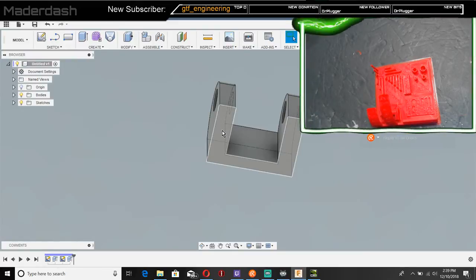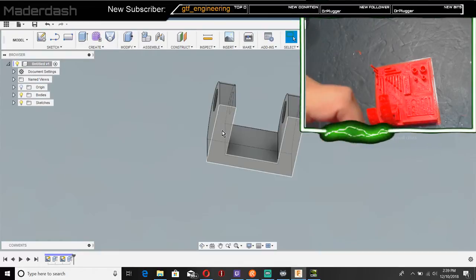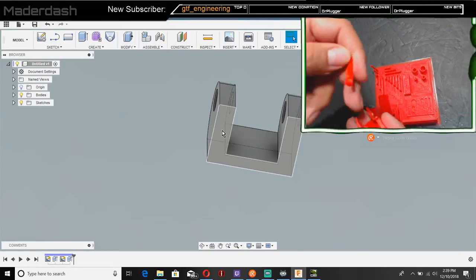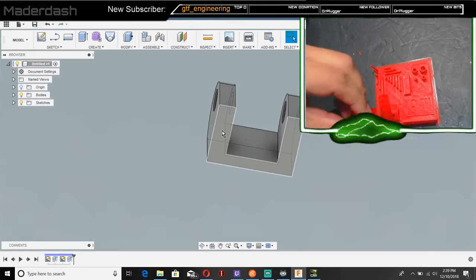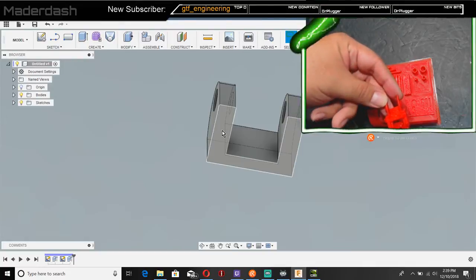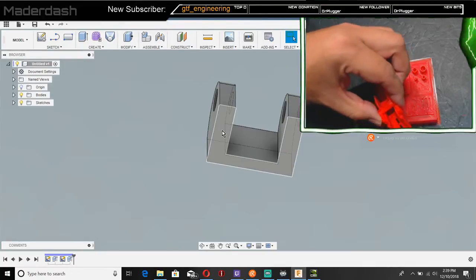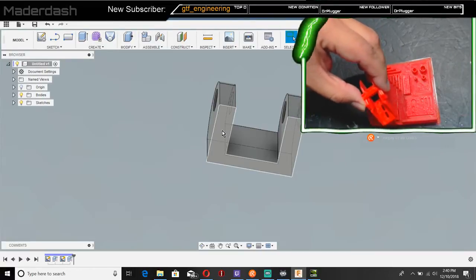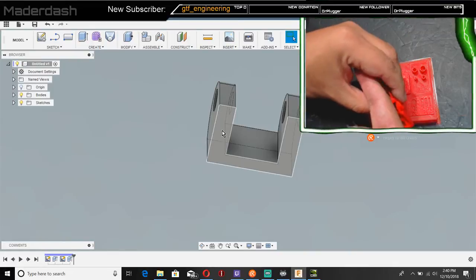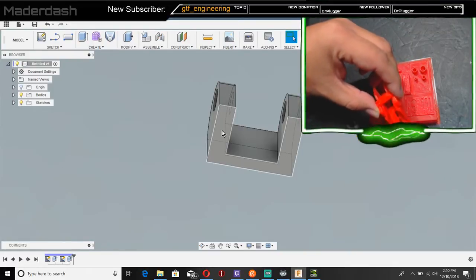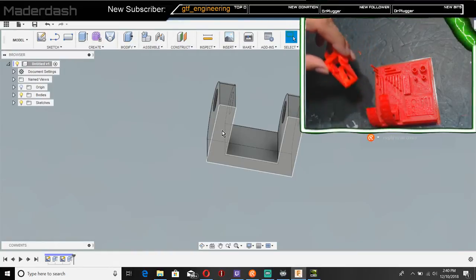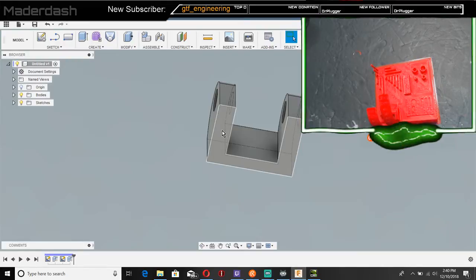Or they are enclosed. And what I mean by enclosed is, see this one here, it's a non-enclosed chain link. It means you could take it apart, add a wire to it, and then put it back on. Enclosed chain links means if you need to add a wire in there, you have to disconnect all your wires and run a new wire all the way through it like a pipe, and then hook all your wires back up. Or if you need to change a wire out, you have to run it through it like a piece of conduit. So I don't want an enclosed chain link.